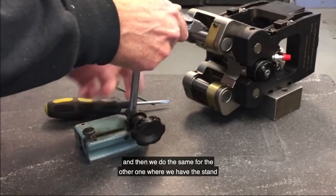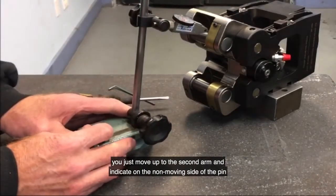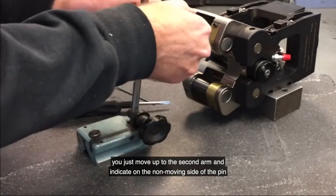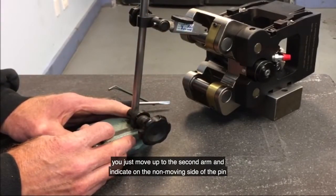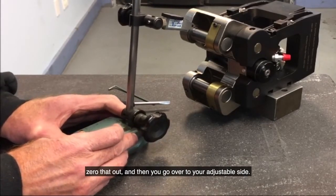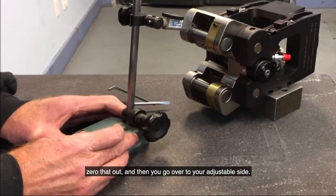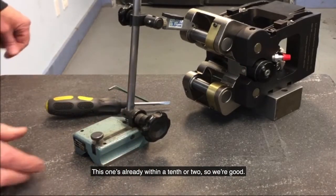Where we have the stand, you just move up to the second arm and indicate on the non-moving side of the pin, zero that out, and then you go over to your adjustable side, and this one's already within a tenth or two, so we're good.